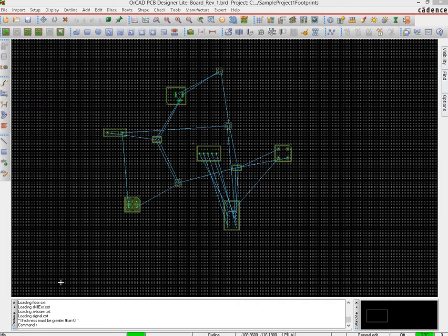After you have placed all the components on the board that you are going to design, the next thing that you have to do is to set the environment up so that it follows the specifications and the limitations which the fabrication house imposes. So now is the time when you navigate to the website of the particular PCB fabricator you are going to use and look up their capabilities and see what they say about minimum design requirements.